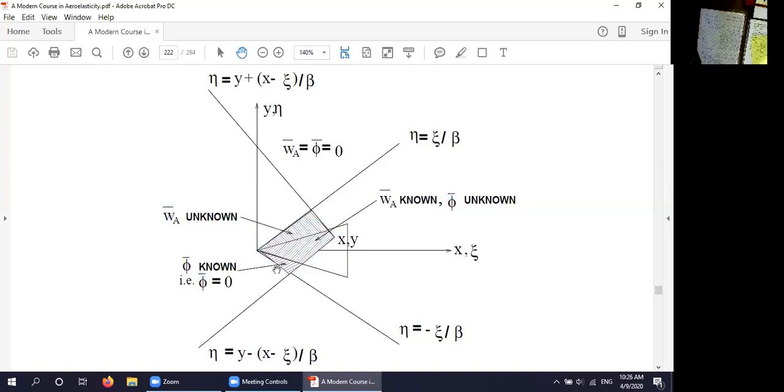But there is further good news. The furthest most point forward, the leading edge tip, if you will, also has Mach lines. That's what these lines are called. These Mach lines pass through that point, and this point can only influence the flow field inside this Mach line and inside this Mach line, which means that this part of the flow field is undisturbed.